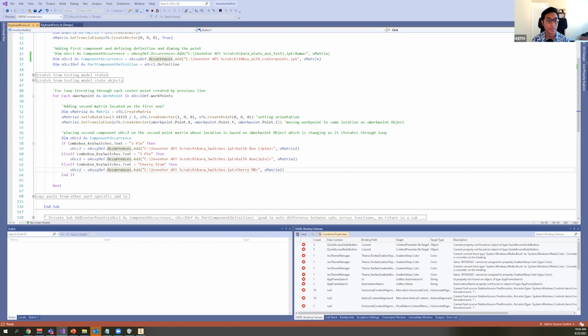And then down here is where you actually get the add function, right? So I'm adding in this particular part. And just a heads up too, I know the API for 2022 is relatively new, and model states in particular are a bit of an unknown to a lot of people, I think, right now. And so after some scurrying around, I found that you were able to place an IPT at a particular model state using this bracket, this caret notation over here. And so these are actually the names of the different model states within this particular part file. Okay, so that's what you're seeing over here.